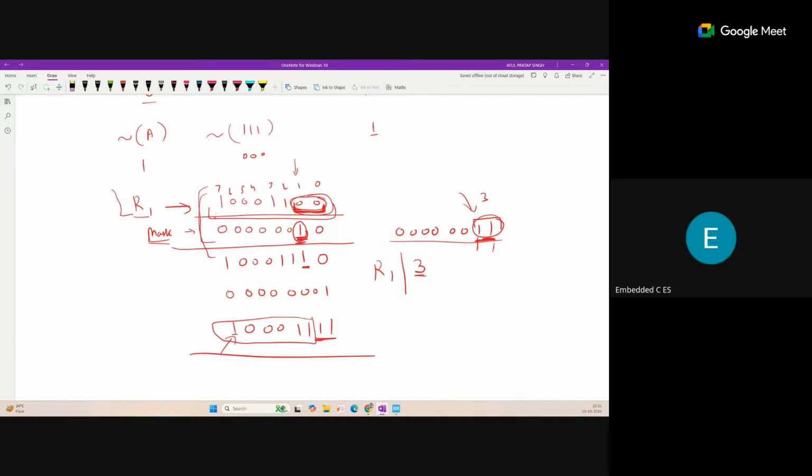If your task is to only update these 2 bits, do not change the other bits. That is why we perform this OR operation, so that the bits corresponding to 0 are not updated, and only the bit with 1 will be updated. So the OR operation is used to set the bit to high.